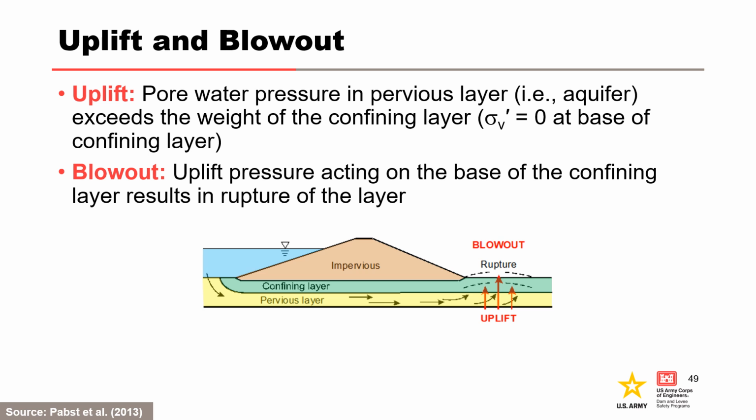When assessing, consider assumptions for seepage conditions, tailwater conditions, degree of saturation, and density of confining layer. Uplift can also initiate in partially saturated confining layers, especially for lightweight soils such as peat or soils with high organic content, or cohesive soils in cases of drought.